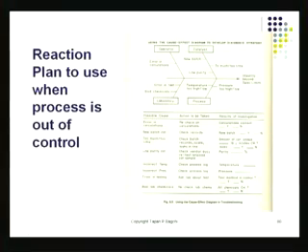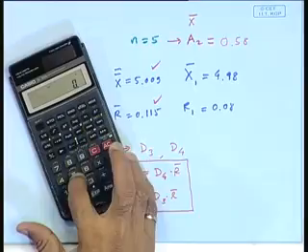Pull out your checklist, and your checklist is this. This is your checklist. And very systematically go over the items, and I've listed them out here. So you notice the factors here, the causes that might have caused, in this case, impurity to go beyond specification limits. Impurities must stay within some specification limits. The first factor is this, error in calculations. So probably some calculations were done using a calculator to adjust maybe the quantity of catalyst or something when this process was running. And perhaps somebody pushed the wrong button here and it created a number that turned out to be different. And if that thing happens, that's actually not so good news.